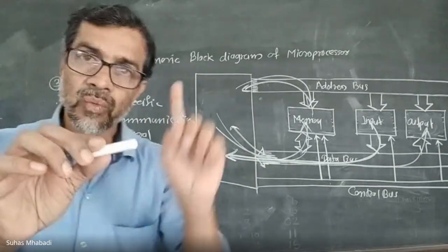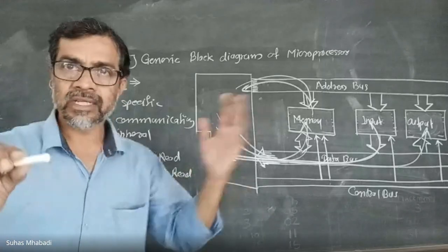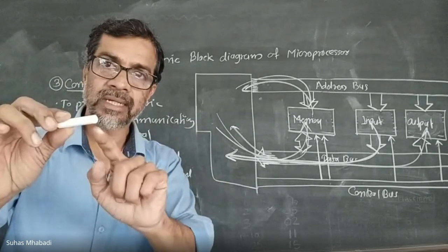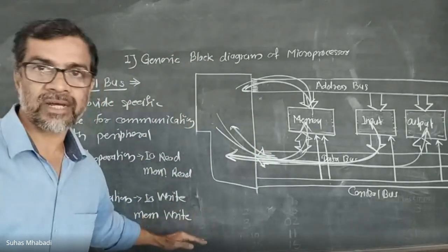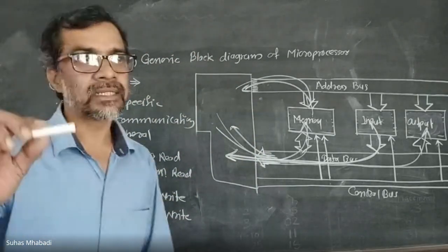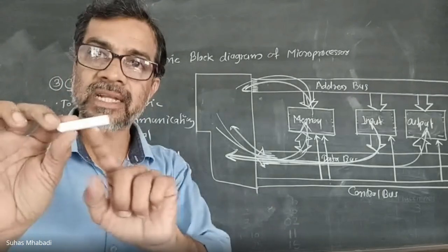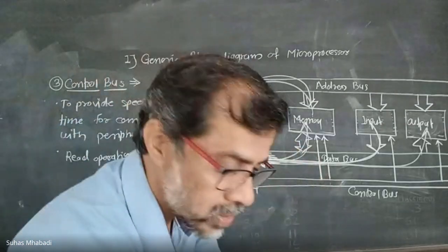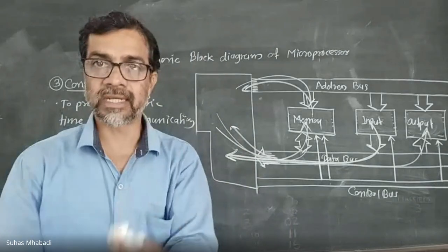If the line is logical one, meaning high, at that moment reading and writing is not possible. But when the line goes low, goes to zero, at that time either of these operations will be carried out. So these lines are called active low lines, and a signal has been named. I require 4 lines, no? 1, 2, 3, and 4. 4 lines are there.